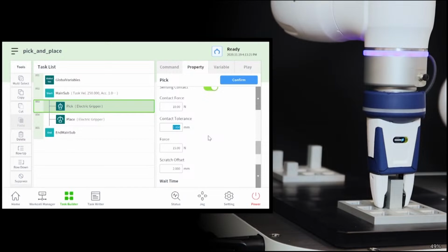As you can see in the video, the height of the workpiece is different, 3 different heights. So the gap between the lowest and the highest one, we have to input, so the gap is 10 millimeter.